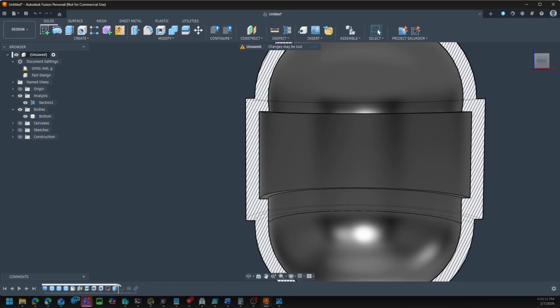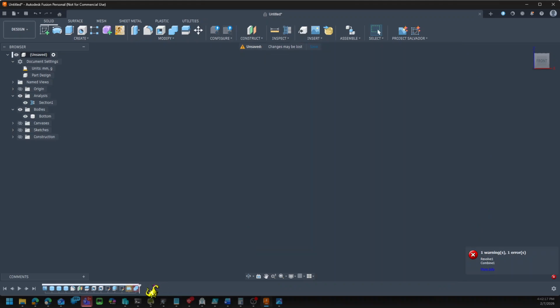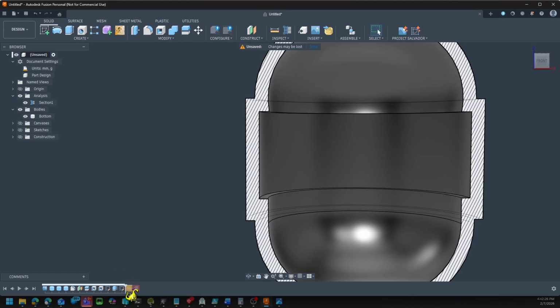Okay. Now I can slide my history marker forward. So I broke it. Now I've got warnings here on these, and my parts have disappeared. Go back. So the last step before the warning is this sketch. And it looks like the reason that it broke there is because these are joined into one body. So let me go back one step earlier.